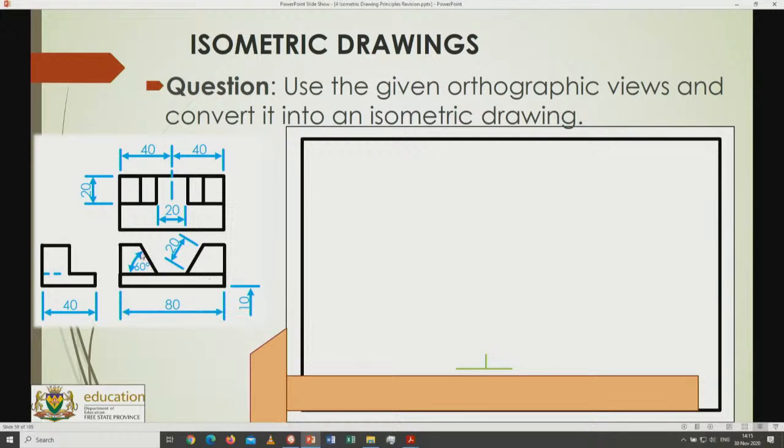So we have to, by means of 60 degrees, work out what that angle is. Now we already work with 30 degrees, and it's basically impossible to work on 30 degrees and to determine 60 degrees on the 30 degrees. So in this case, we talk about non-isometric lines, in other words, lines which are not either straight upwards or 30 degrees to the left or 30 degrees to the right. That means that we will have to work accordingly by saying, right, we have to find the angle, and then on that angle we can draw it in onto the part.